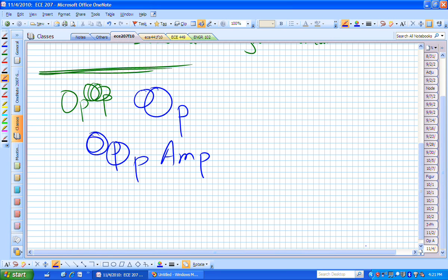You could say, okay, suppose that Vn is positive, then what's going to happen at V0? Well, that's going to actually give you a minus V sub D, which will get amplified, so you're feeding back a negative signal, and you put in a positive, so it is trying to force that positive signal to a smaller value.